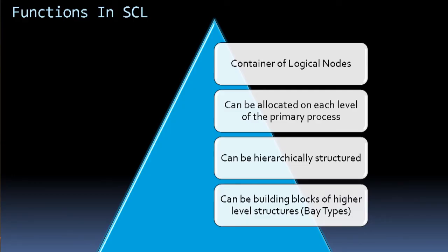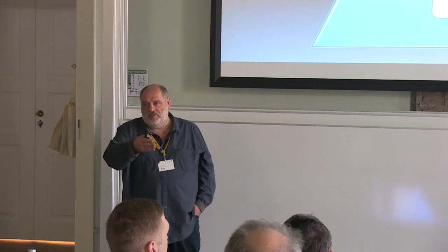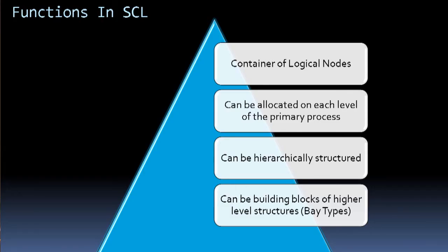This hierarchical structuring can be used for different purposes. So sometimes people are coming and say, I have as a base protection functions for the substation. Then I have distance protection, overcurrent protection, differential protection. So there's a classification scheme for my functions. This classification scheme may make sense when I build function libraries. So there I can use a hierarchy. I can have a hierarchy in the measurements, current measurements, voltage measurements, for instance.